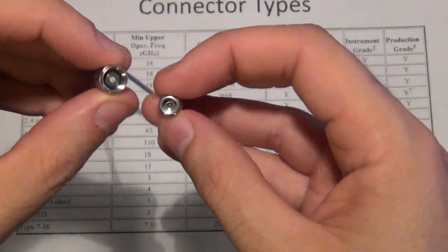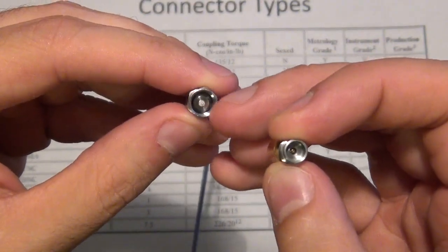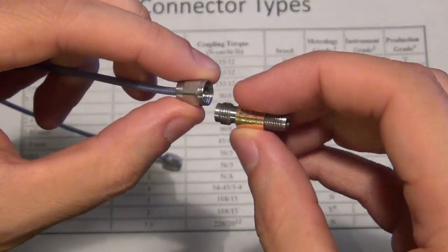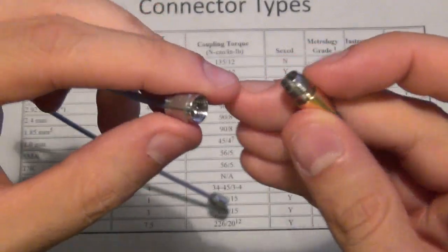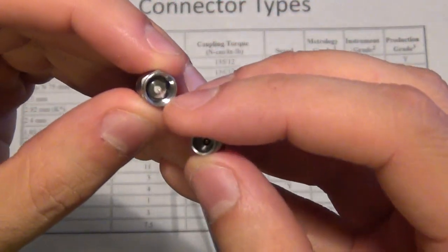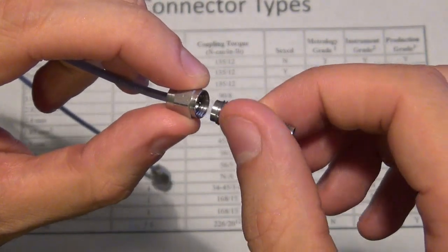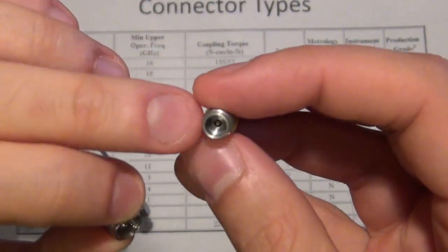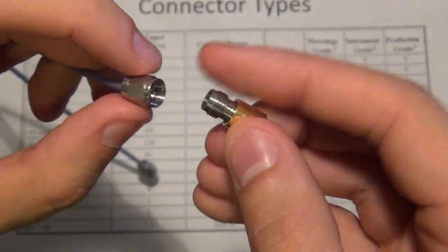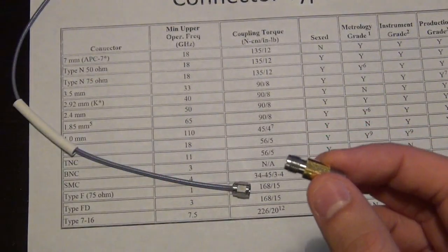This is because when these connectors get screwed together, the ground, which is that metallic flat part, has to come in contact with the metallic flat part. Basically, the outer shell of the cable has to connect to the outer shell of the connector. If you allow this connector to turn while you're screwing them together, those two surfaces eventually end up rubbing against each other and wear each other out. Even worse, the center pin of the male connector, when it is in contact with the center pin of the female connector, if you allow this to continue to turn, they will rub against each other and wear out, and you can damage the female center connector of this particular one, and that's also very bad for the connector. So what you want is a way of holding on to this connector without allowing it to spin.